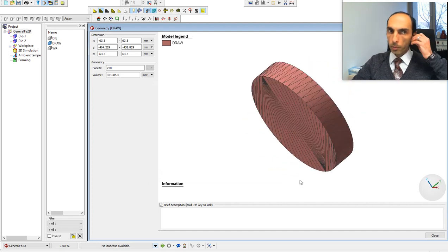Okay, now we have to set. First, we should allocate the available geometries to the associated parts here. The information of the die, for example the initial diameter, the final diameter, the semi-angle of the die, alpha, and other parameters for this die are given in slide number 6. So you can check it if you want. And even the relief angle is given, 54 degrees.